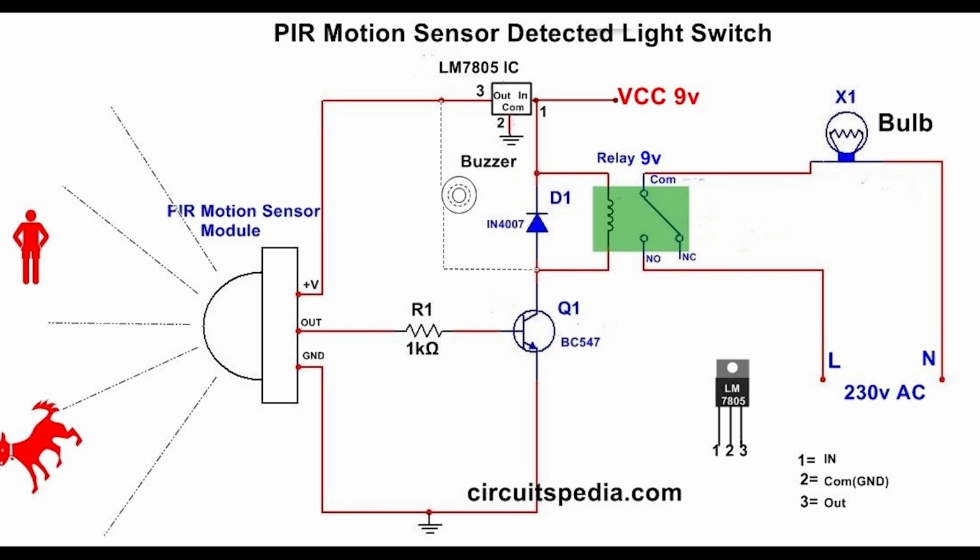According to these data sheets for the 5 volt series, you can easily figure out this series of regulator ICs. Just 3-pin ICs like a transistor. I think it's a TO-220 package. I have never seen any SMD model, but it could be possible, I don't know.